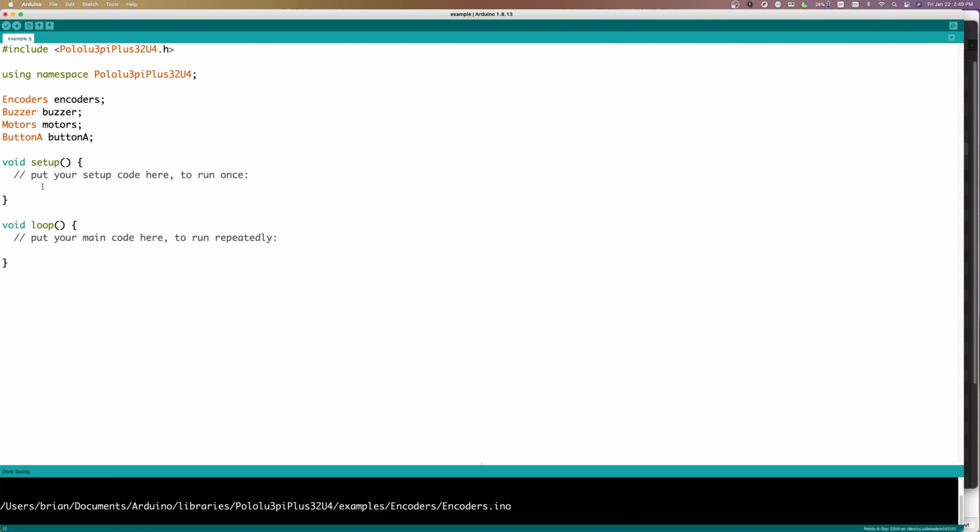One thing that I want to set up is my serial connection so that I can use my serial monitor. We do that by typing Serial.begin and providing a baud rate at which we want to send information to the serial monitor. I will show this on the serial monitor in a few moments when I actually use that to display some output. So for right now, we're going to leave that like this.